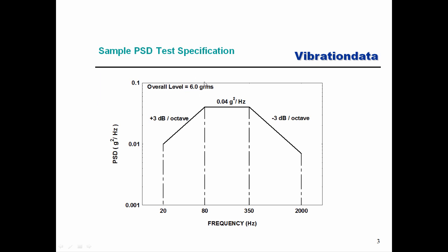And in some sense, it represents the severity of the input level. But obviously there's more to the story because we're also concerned about how this energy is distributed with frequency. And then the next step of concern is, well, what is the natural frequency of our piece of equipment that will be tested to this PSD?